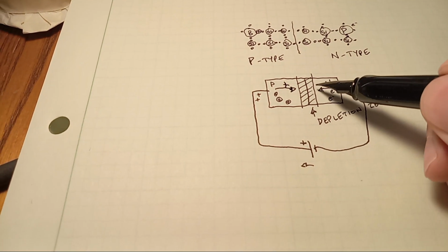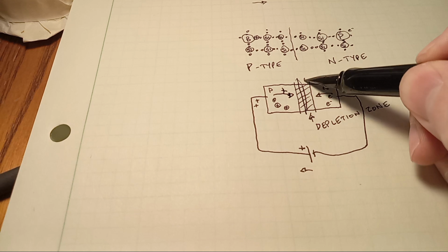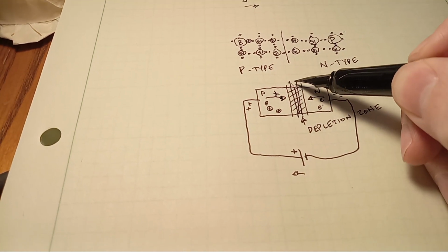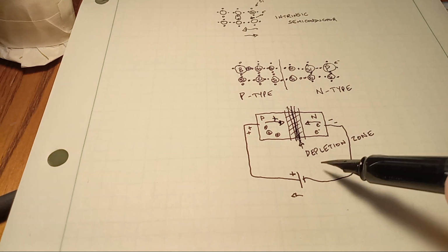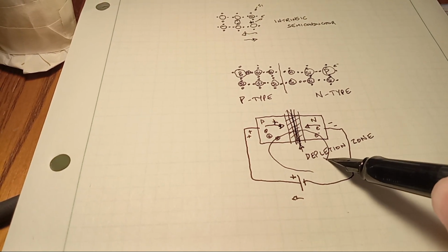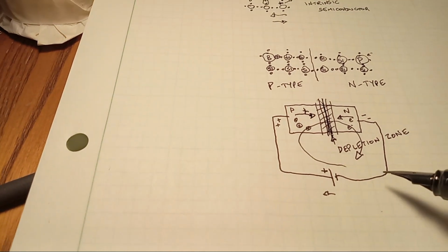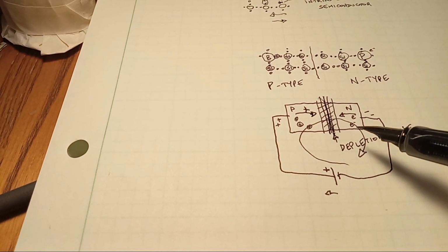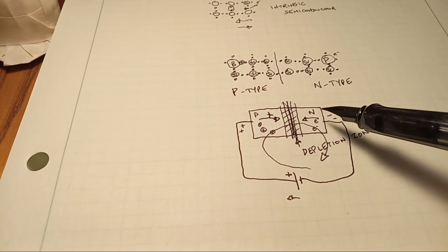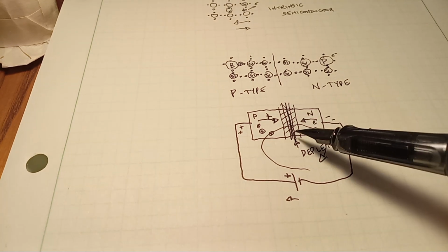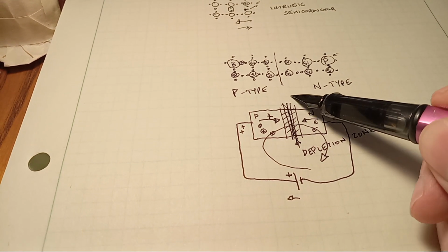The effect this has is to make the depletion region smaller. Apply more voltage, it shrinks further, until it stops existing entirely. Current will now flow through the device. One way to think of it is that extra holes are added on this side, extra electrons are added on this side, and then at the middle, the electron falls into the hole.